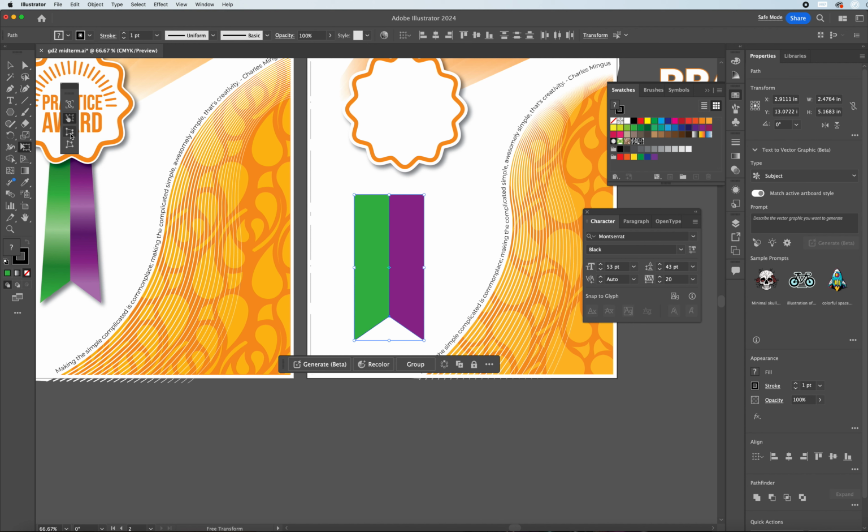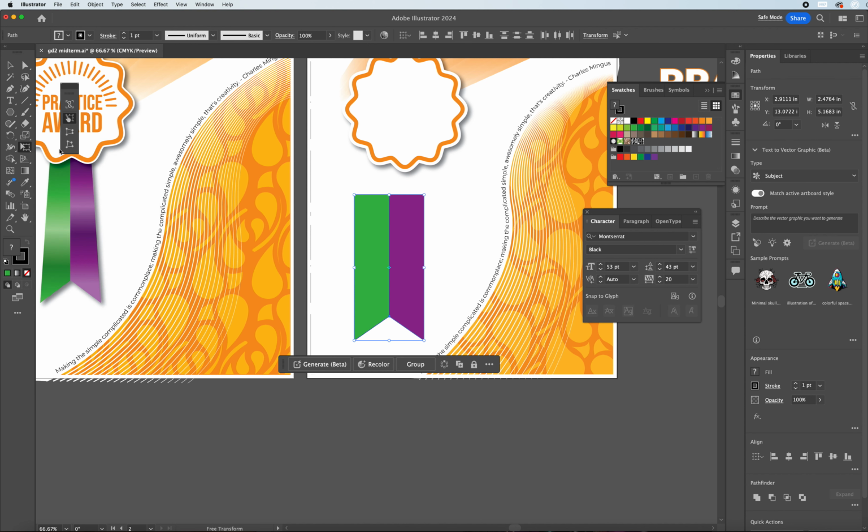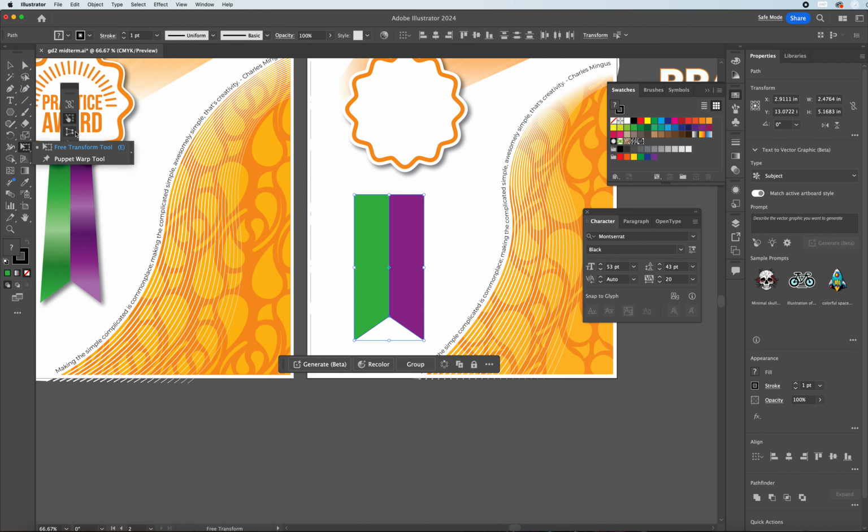With a free transform, over on the left side navigation, it's very beneficial in either modifying out an angle or adjusting a shape or object to what your preference is. Looking on the left side navigation, we have the perspective, free perspective tool, or perspective distort. With this, I can get into scaling up an object left or right, but just be careful because the perspective is a little bit restrictive. It works out very well for what we're trying to convey.